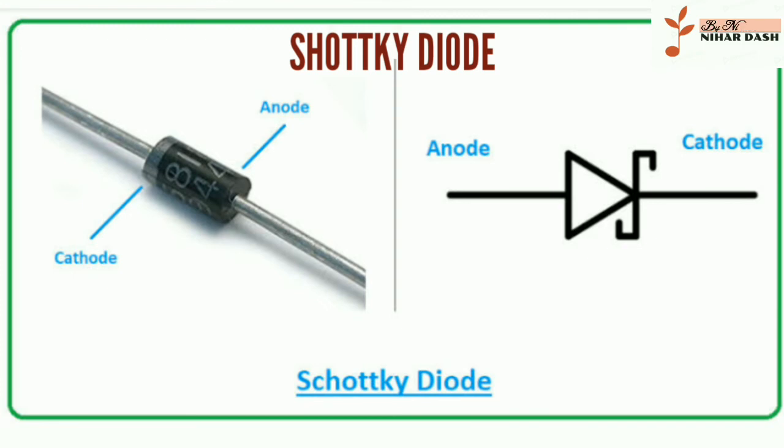This junction is known as a metal semiconductor junction or MS junction. A metal semiconductor junction formed between a metal and N-type semiconductor creates a barrier or depletion layer known as a Schottky barrier. Schottky diode can switch on and off much faster than the p-n junction diode.